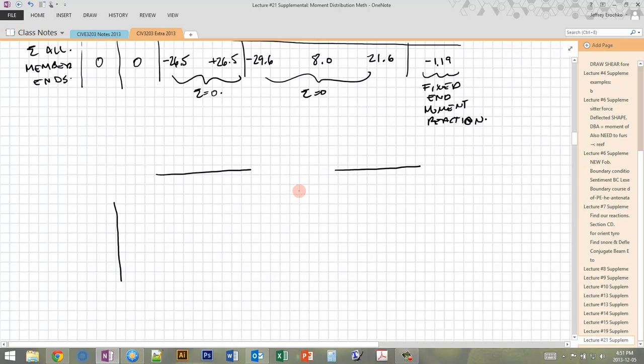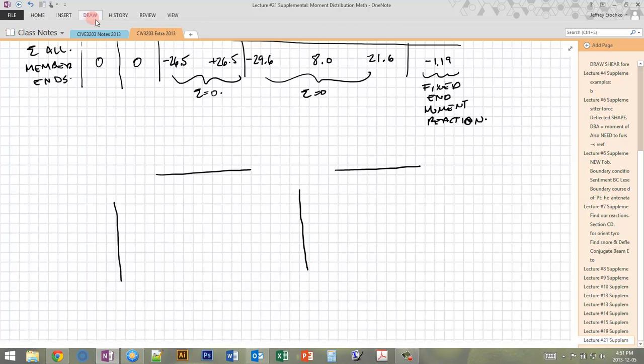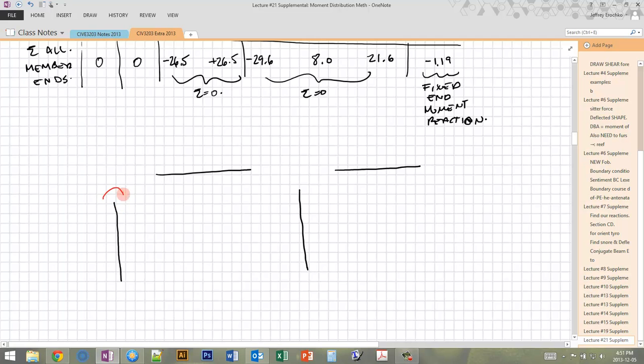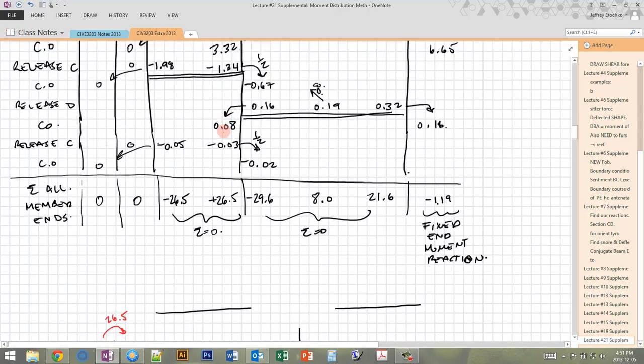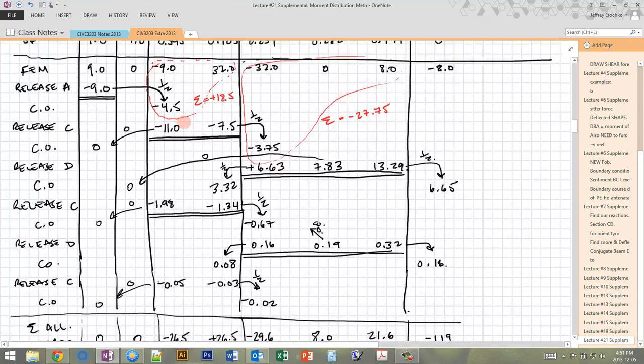I know this is quite a long video now, so bear with me. So now I know all the moments. At the bottom there is 0. Here I have 26.5, right? And again, positive. So this one is CA.